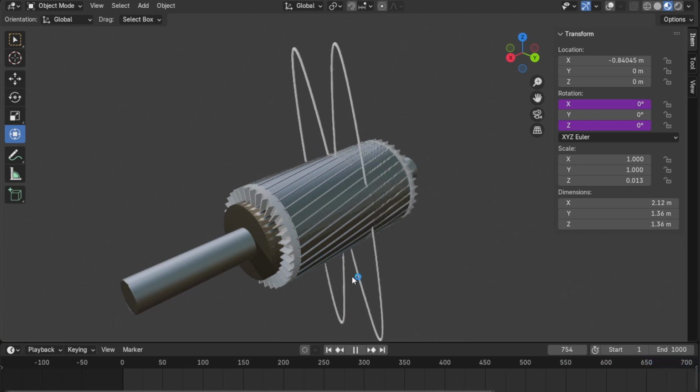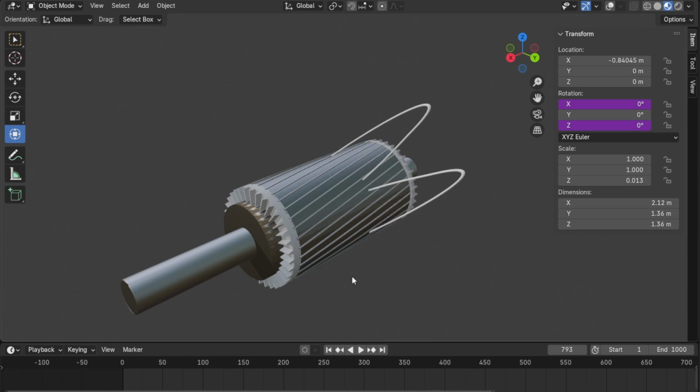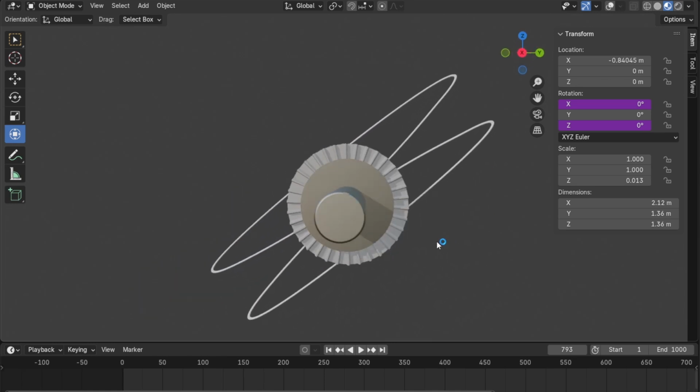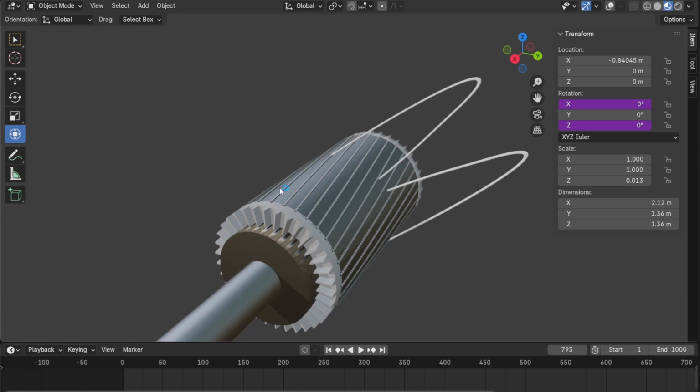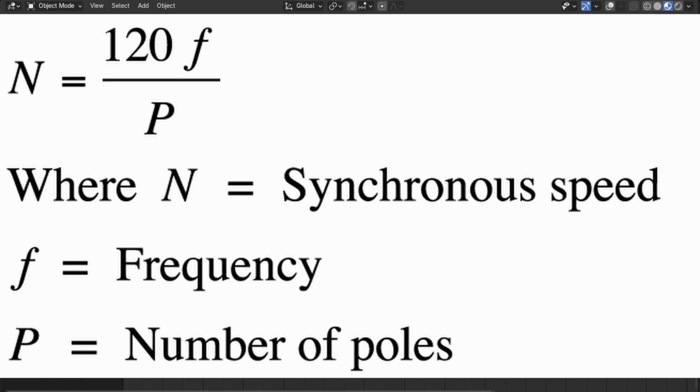Okay. And next thing I want to think about is inrush current. All right. Where does inrush current come from and why does it happen? Well, it happens because this rotor is stationary when that contactor first pulls in in 99% of cases. So when the contactor pulls in, this rotor is completely stationary. But if we think about this synchronous field, the stator field, it's the synchronous speed, and the synchronous speed never changes.